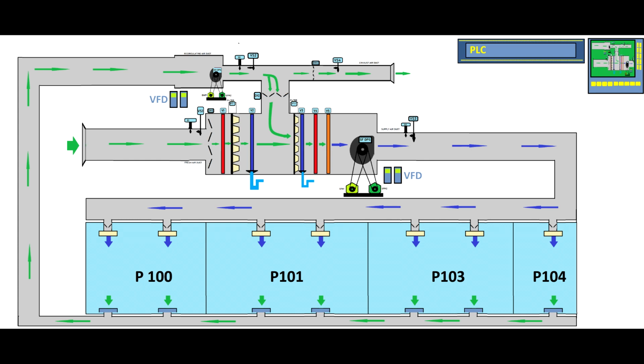In this picture you will see a very poor design. An air handling unit provides air to a group of 4 rooms, but this ducted system is not provided with a CAV or with variable air valves, although we do not have reheaters. So we have a global airflow measurement at the origin where the air handling unit is pushing the air into these rooms. So I do not have any chance to heat or to cool the rooms separately.